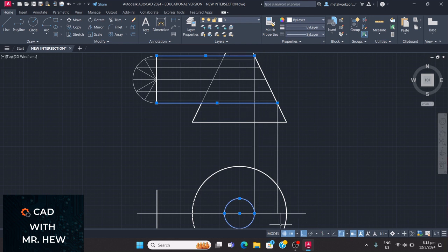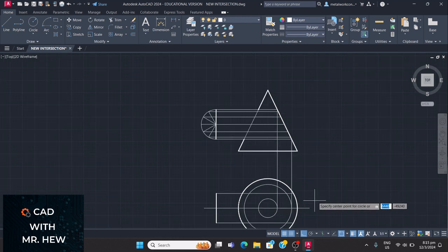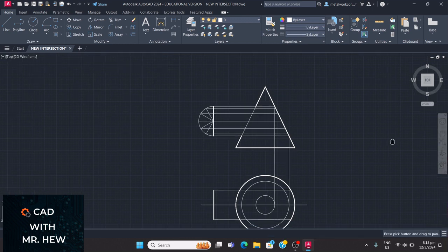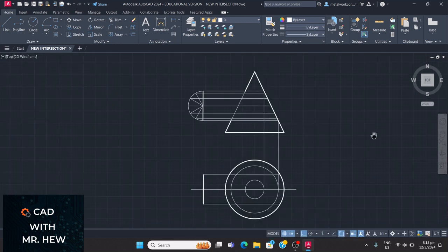And what we're gonna do now is draw the largest disc for the cut between these two horizontal highlighted lines in the front elevation. Okay, so we're gonna go center, radius there, and that would be the largest circle. See, let me show you. Right, that's the largest circle. Okay, so this one is the largest disc. This one is and this one is the smallest. This between that cut and this cut on the front elevation of the cone.